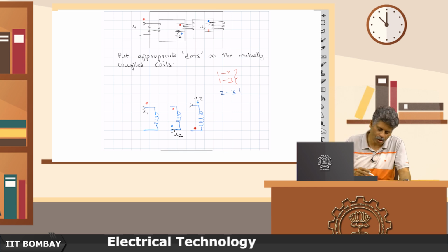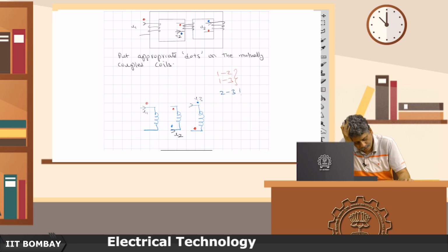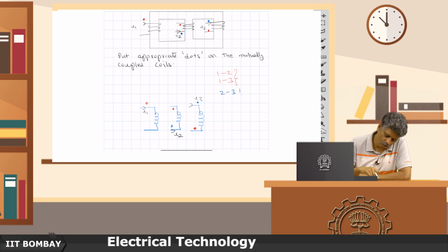So now all the polarities from 1 to 2, 1 to 3, 2 to 3. Because 1 to 2 is done, then 2 to 1 is also done. So that is why I do not have to redo 2 to 1. So only 2 to 3 is required, and then for 3 I do not have to do any separate exercise, because 1 to 3 is already done and 2 to 3 has also already been done. So this is the dot polarity.